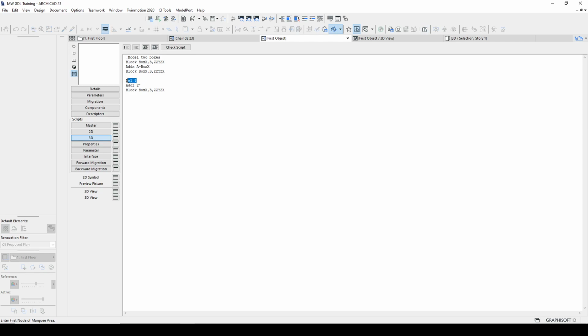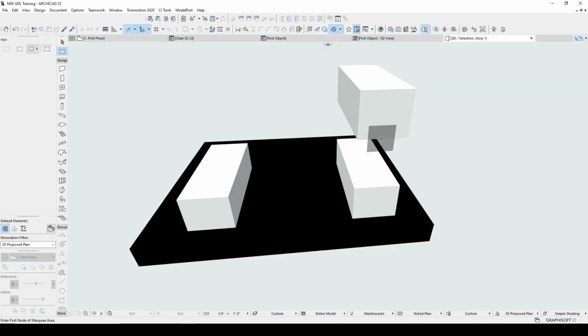Let's see what happens if we eliminate that del 1. Press to save. Go back to 3D. So now we drew a box. We moved our origin. Drew another box. We moved up 2 feet. We drew another box. Very different experience. So you need to keep track of where your origin is. Often a good practice to do a del top every once in a while, which gets you back to your 0, 0. So you don't have to keep track of exactly how all of those transformations happened.